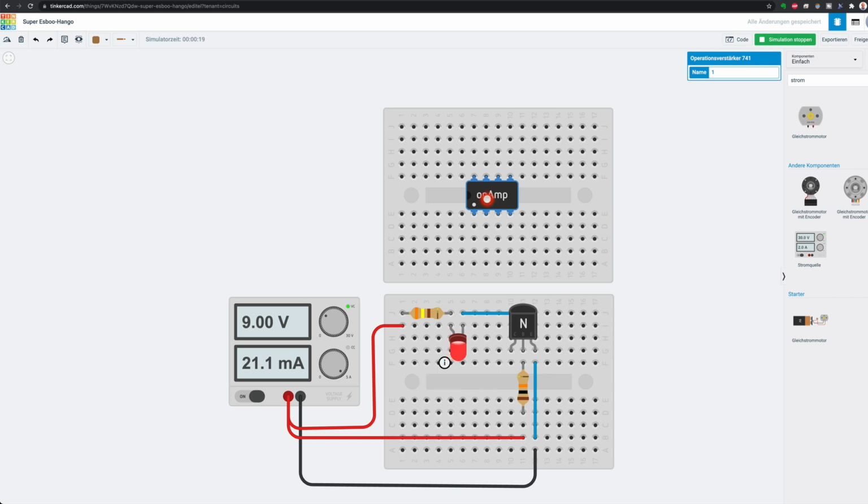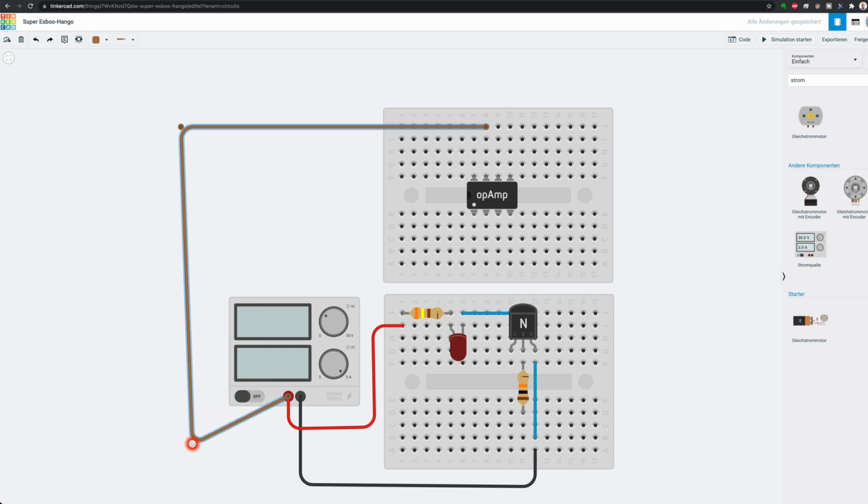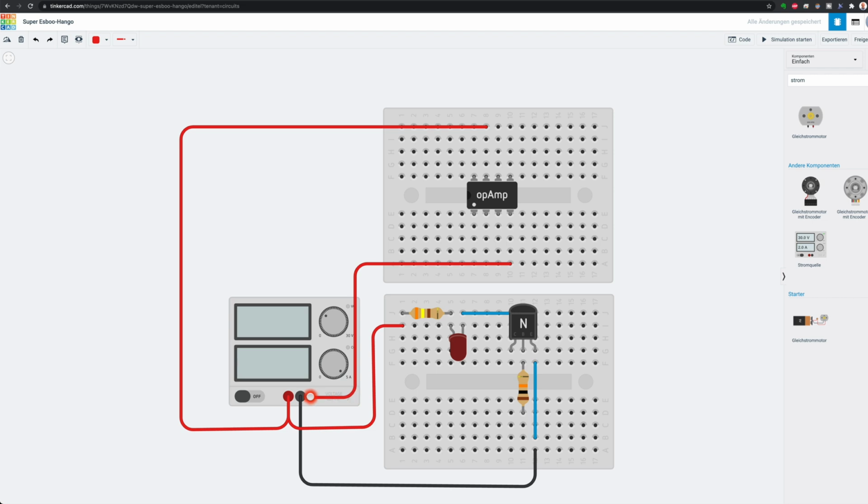Now what we want to do is use this operational amplifier on this additional breadboard up top as a switch in order to trigger this signal, which now enters the transistor from the power supply. Let's stop the simulation, let's remove this signal line here, and let's properly connect the operational amplifier. First let's connect the positive power supply, which is this pin here. Let's draw a connection to this connector here. Let's angle it a little bit to increase the overview over our circuit. And also let's change the color to red to make it clear that we have a positive power line. This connection here, power minus, leads to the negative power supply. And in order to also get this fed into the power supply, let's draw it down here and enter it here and color it in black to make it clear that it's a negative power supply line.